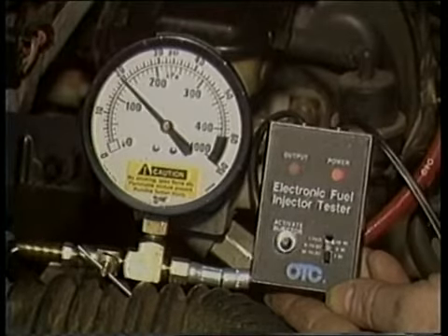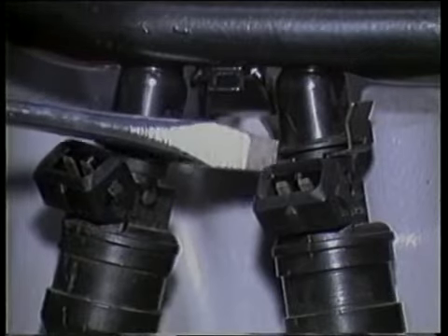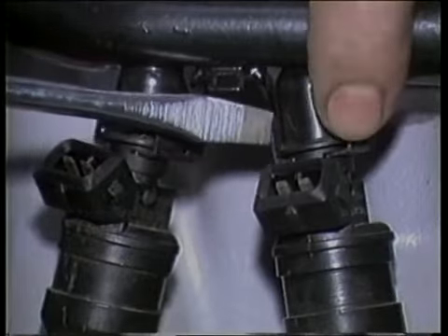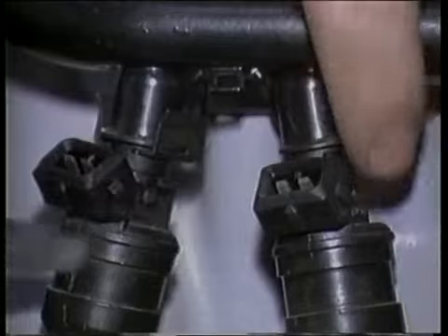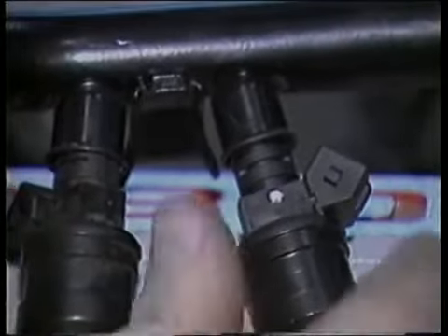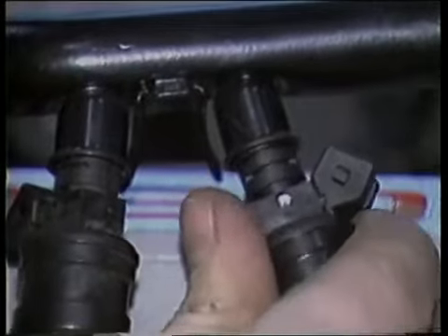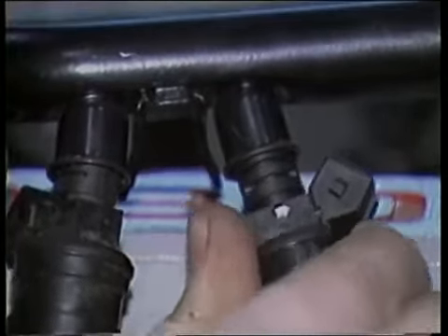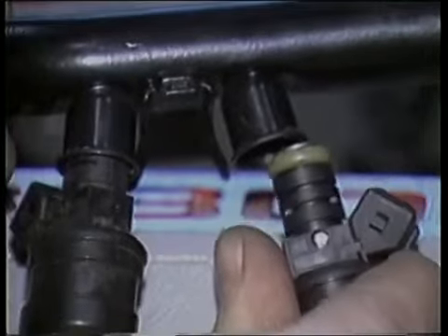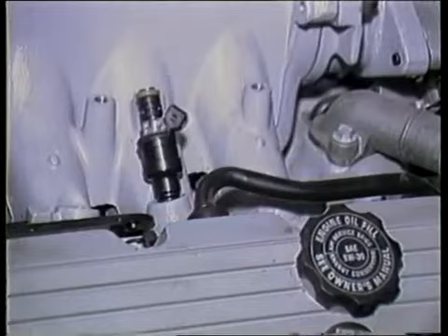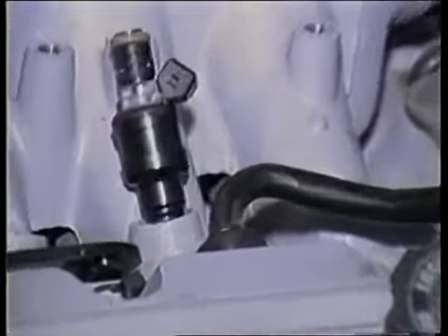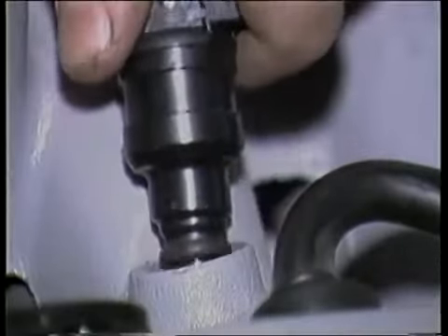Replacing multi-point injectors is not difficult. Often, small clips hold the injectors on the fuel rail. The clips snap into a groove formed in the body of the injector. When the clip or any clamp in the engine is removed, the injector will pull out of the engine and out of the fuel rail. Always inspect and preferably replace any seals when servicing the injectors to prevent fuel or vacuum leaks.